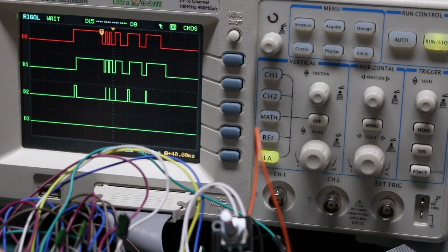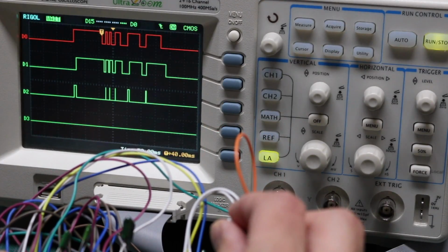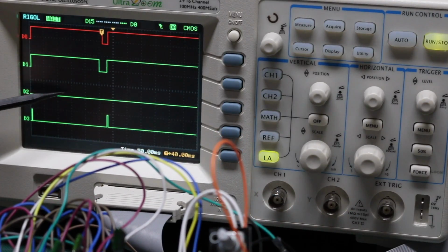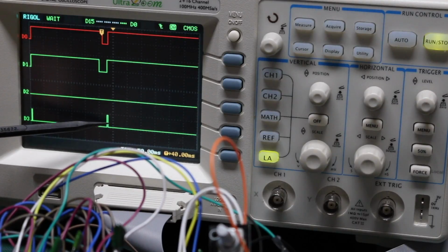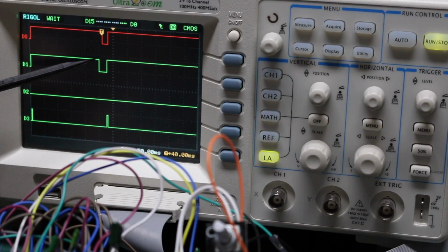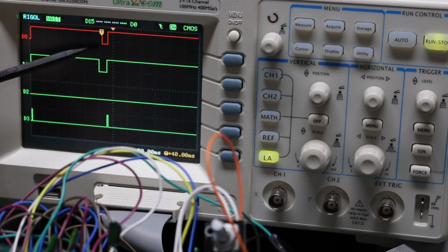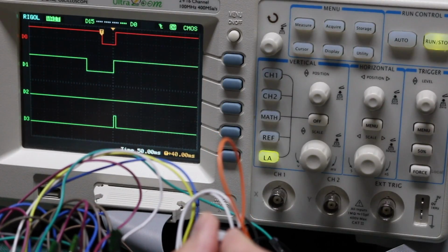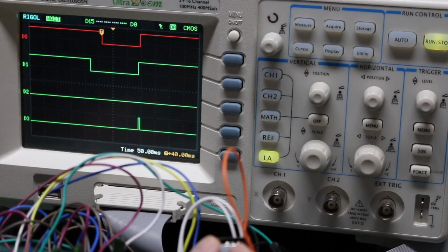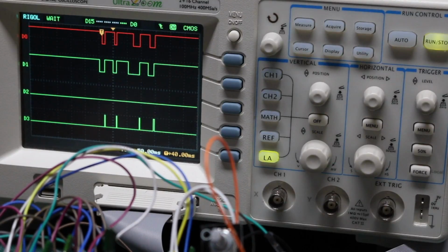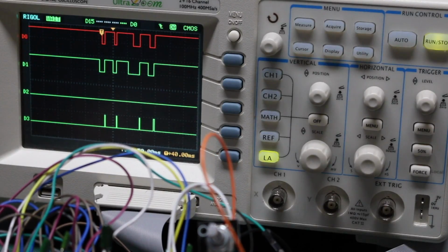So now if I go counterclockwise, just a single one, well, I accidentally did 2. So now clockwise out is quiet, but I'm getting a counterclockwise pulse, and output B from the encoder is what went low first and then A. I'll do more counterclockwise turns. There's another one, and I went slower, so it took longer to complete the rotation on A and B. I'll try several, and there's 4 hits that all registered properly counterclockwise.